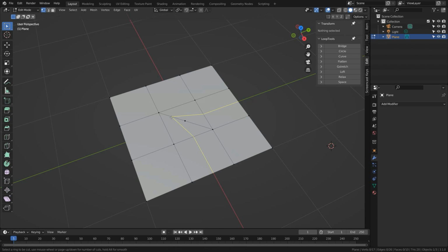But what it means is that there's a new direction of pull away from our vertex here, and it causes problems, especially when it's on an area of curvature or a corner. So we do our best to keep these 5-spoke poles on as flat an area of the mesh as we can find. Now that's not a very useful demonstration of anything you'd want to create in 3D, so let's start to think about how they actually turn up, and what we need to do to control them.